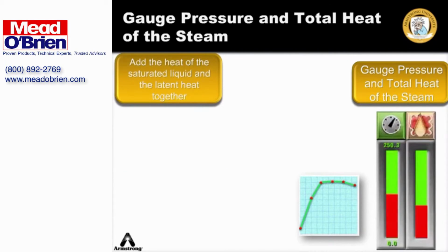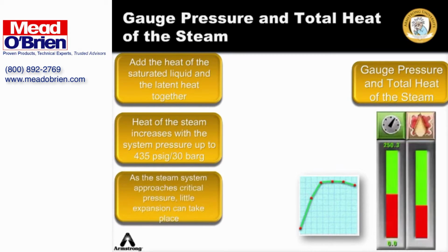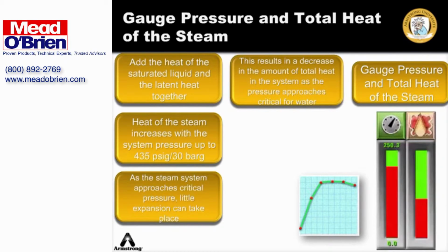Add the figures for the heat of the saturated liquid and the latent heat together, and the sum is the total heat of the steam. The total heat of the steam increases with the system pressure up to approximately 435 psig. Beyond that, the total heat decreases with increasing pressure. As the steam system approaches the critical pressure, little expansion can take place. The amount of latent heat added to vaporize the water begins to decrease rapidly due to the increase in sensible heat needed to bring the water to boiling temperature.